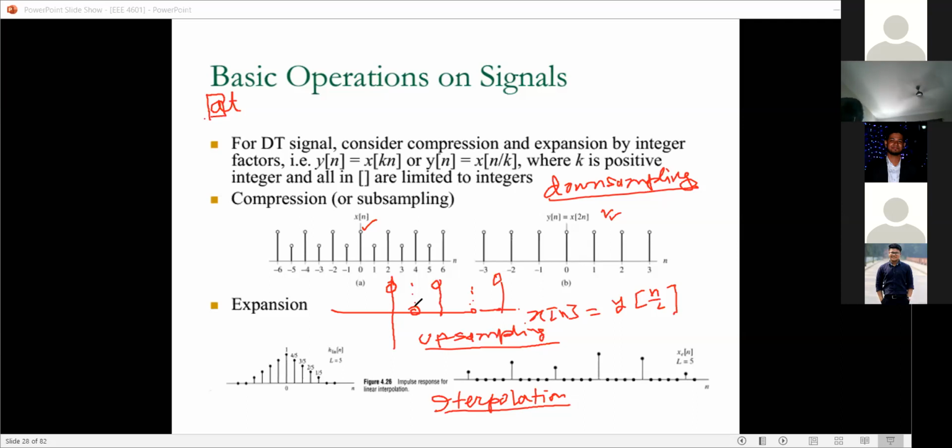For example, an averaging technique can also be used there. Say if we make a running average of this signal, that means we are adding these two samples and dividing by 2 and replacing the 0 by this value, okay? Then your signal will be something like this, isn't it? This 0 will be replaced by the average value of 0 and this signal. This is one of the interpolation techniques. So there exist many other interpolation techniques.